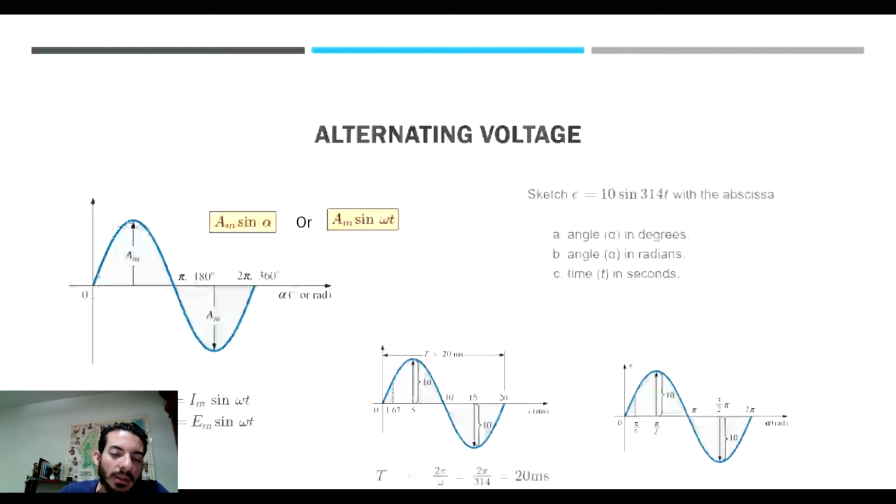So if I ask you in a quiz or a question for the exam, what is the standard voltage, what is the standard frequency? U.S. industry, U.S. homes and apartments, it's going to be 60 hertz. Now the voltage is usually 120 volts, and that really depends on the transformers and things. Could be all the way from 115 to 130 volts. So by rule of thumb, the RMS is usually 120, and we'll talk about that also.